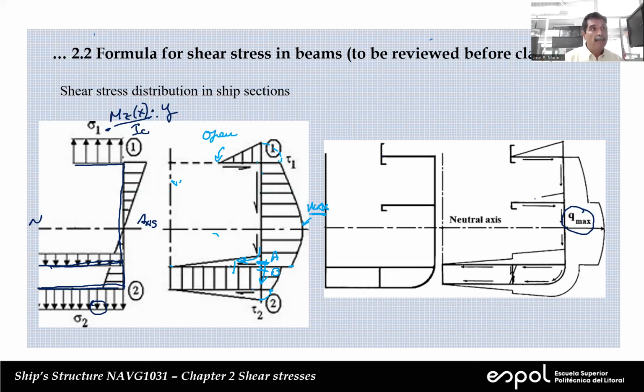Do you remember how to calculate tau from little q? From little q over t. Exactly. So at any point where you want to calculate the shear stress, you make a cut, calculate the value, get the little q and divide it by the thickness at that point. And that's it.